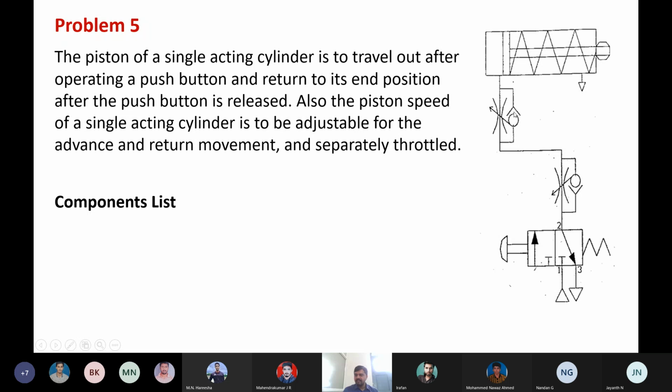because air pressure is applied in the downward direction. The poppet cannot move upwards. Because of that, there is a path for movement of air. Once again, when it tries to escape through this path, because it is in the downward direction, this poppet will move downwards and it will block this path.